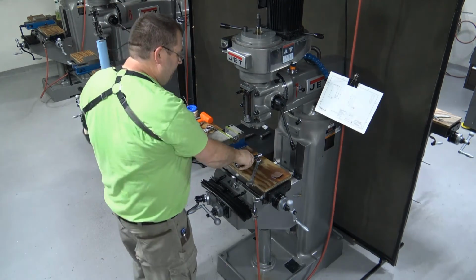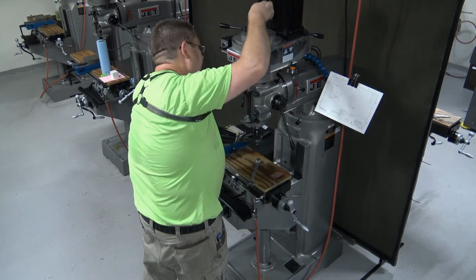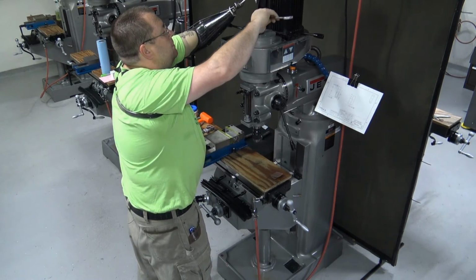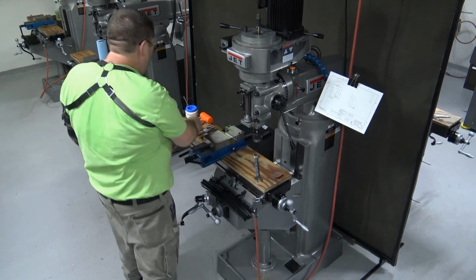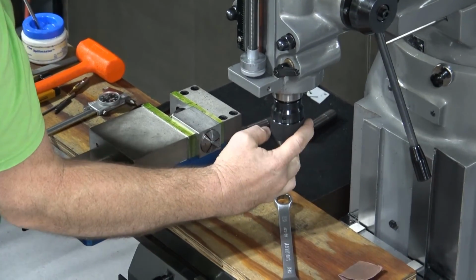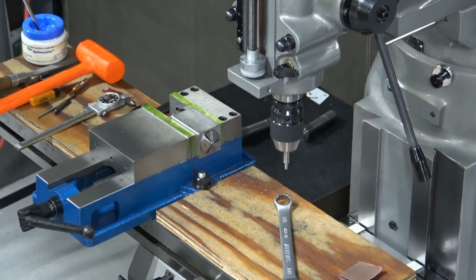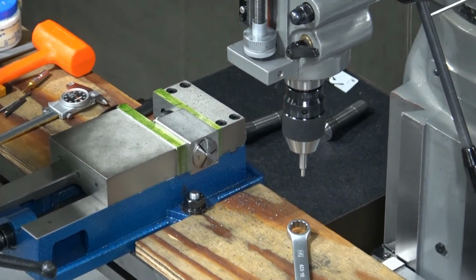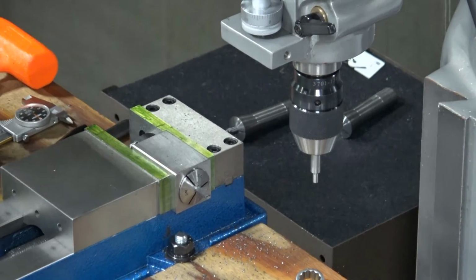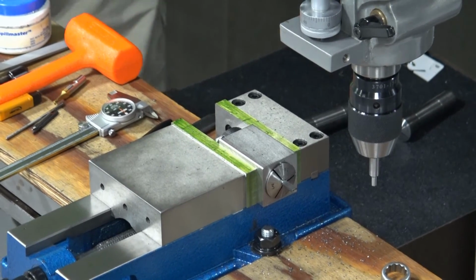I need to make sure that I have enough height because the reamer that we use has got some length to it, if you remember. So if I don't get high enough, I'm going to have some issues. I'll tighten up that drawbar. Set my edge finder in. You can see that if I'm just down in the shop making things happen, these things come together relatively quick if you have a good understanding of geometry. You don't have to be a professional machinist to understand geometry. Geometry is going to be one of those things that's going to help you out a lot as an engineer in the future.